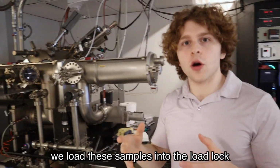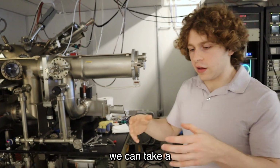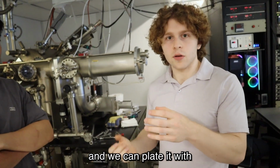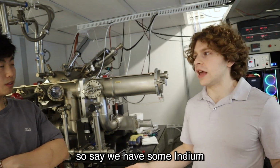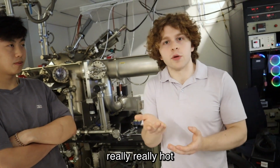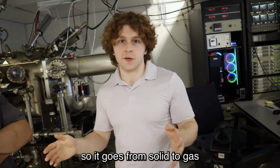And so what we do is we load these samples into the load lock, let them depressurize, then load them into the main chamber. And when we do that, we can take our sample and plate it with material from a source. That source material is a solid phase crystal of whatever material we want to grow. So say we have some indium we want to grow, right? We take a crystal of indium and heat it up really, really hot. And when we heat that sample up, what happens is it sublimes. So it goes from solid to gas phase.